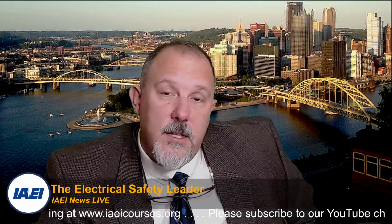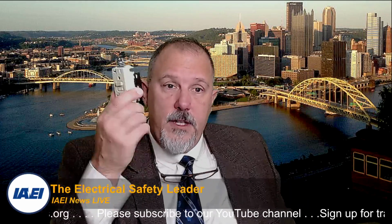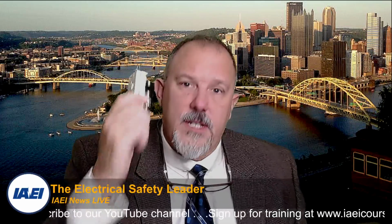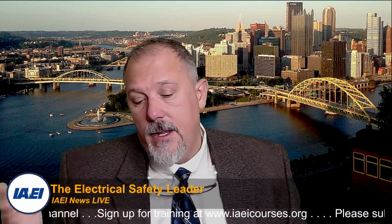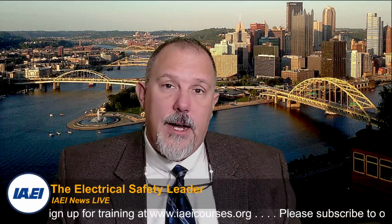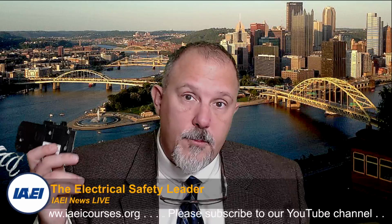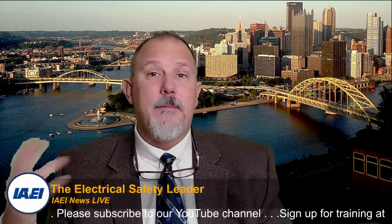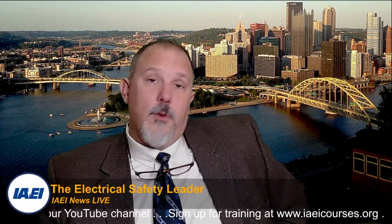What those third-party devices are there for is if you have, remember, these devices here, I can have downstream of this, I can have all standard receptacles. Downstream of this, I can have all standard receptacles. I'll tell you, in this house here, I don't have any GFCI receptacles in my house. I have GFCI in my circuit breakers. Now, if an inspector came here when I'm selling it, and they went to my bedroom or my bathroom and they went into my kitchen, they would say, you don't have any GFCI receptacles. And I would say, that is true.